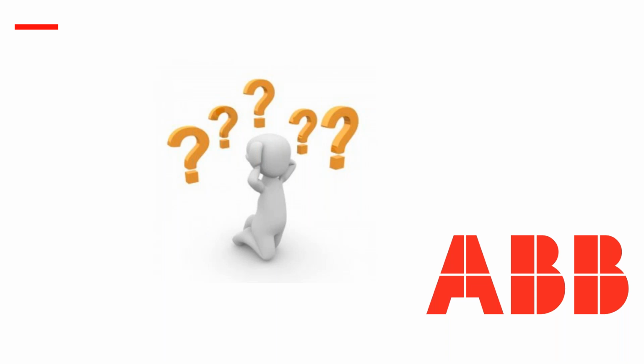Do you need to use a contactor when using a soft starter or VSD? Yes. Some VSDs do have contactors inside. If you go with ABB variable frequency drives, they have AF contactors in them.